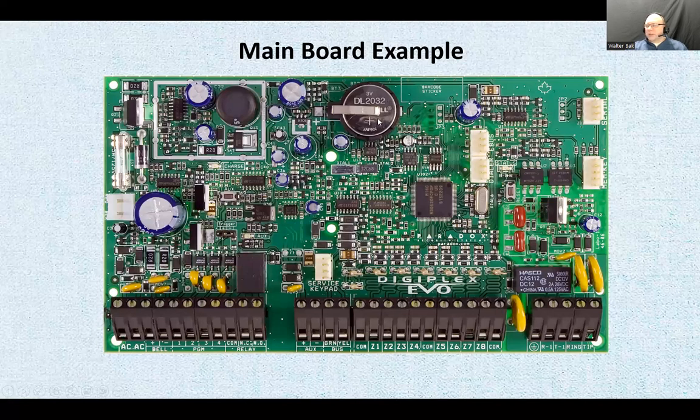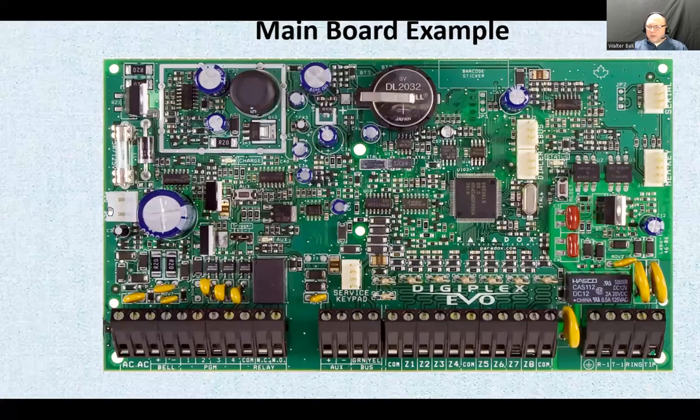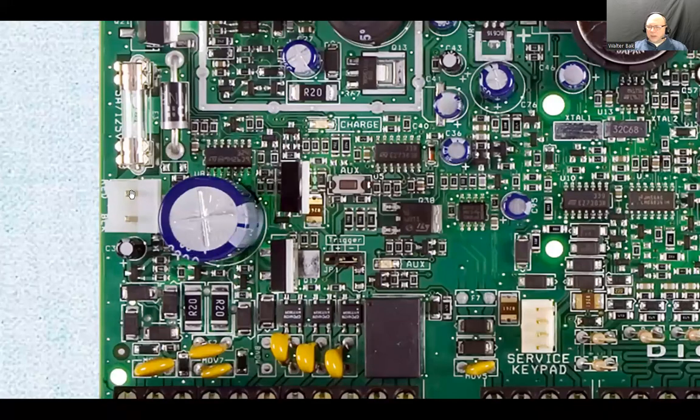Well, here first you see that watch-type battery. This keeps all the memory that has to do with the date, hour, and some other things, just like a computer BIOS type of memory. If we move towards the left here, I'm not sure if you can see this or not, but here is a connector. And if you look carefully, you're going to see something that says red and black. This is the backup battery connector for the security alarm.